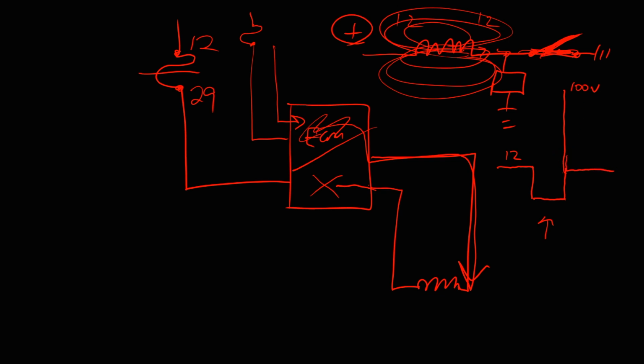That's what it would look like if you looked at a solenoid, a relay coil, a fuel injector, anything that makes a magnetic field. When you turn it on, turn it off, that's what you're going to see. So if I'm taking a transmission solenoid and I'm pulsing it on and off like 100 times per second, how many of these spikes am I making?